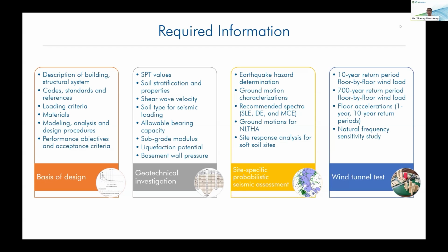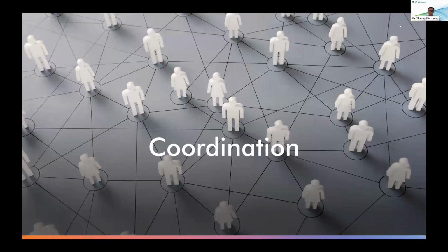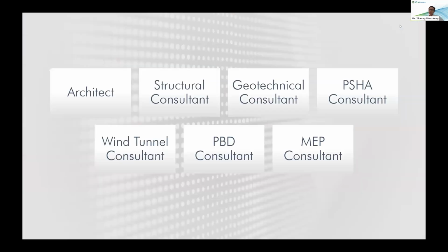They also conduct a natural frequency sensitivity study for their wind loads, because our finite element models are not exactly the same as the actual building response. When we measure the natural frequency of buildings that are already constructed, they are different from our finite element model. So to consider that effect, the wind tunnel consultant conducts the frequency sensitivity analysis.